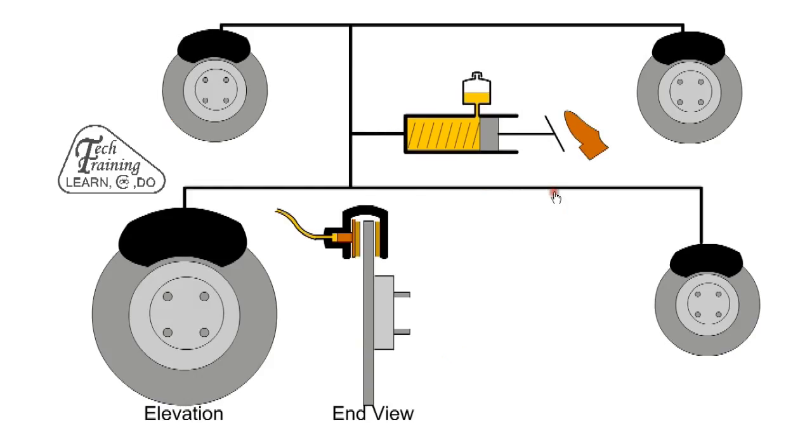With a hydraulic system, when we apply a force to an incompressible liquid, the force is transmitted throughout the fluid. By adjusting the size of the pistons, we vary the available force and the distance travelled by the slave cylinder. Here we see the master cylinder with a reservoir for brake fluid on top. When the pedal is pressed, the piston moves forward and closes off the inlet from the tank. The fluid is then pressurized and activates the slave cylinders.